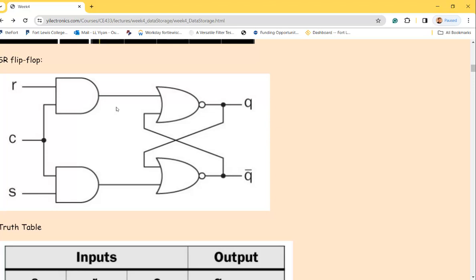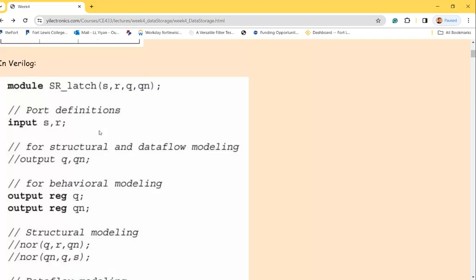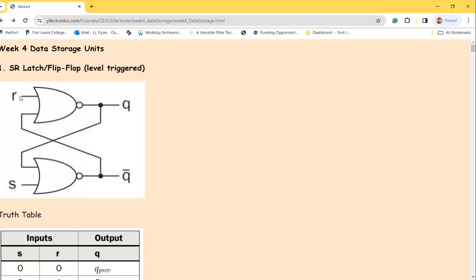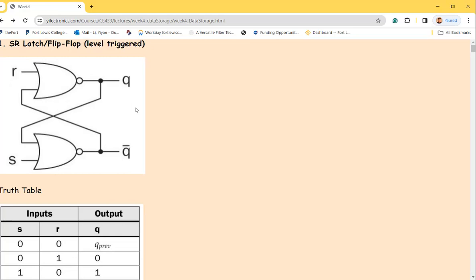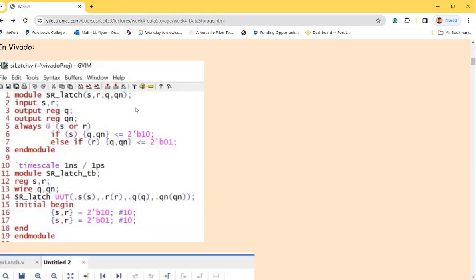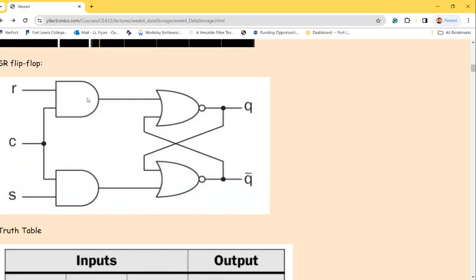So what's the difference between the latch and flip-flop? So flip-flop is getting clocked. So you are controlling the output by a clock. It's a combinational logic circuit. If you don't control it, whenever this one changes, you get Q updated. It's not controlled. Sometimes you want to control it, like a latch on the door. You open the door, the data will be sent out. Otherwise, they stay at the previous state. So when you want to control it, you have to add another stage in front of it.